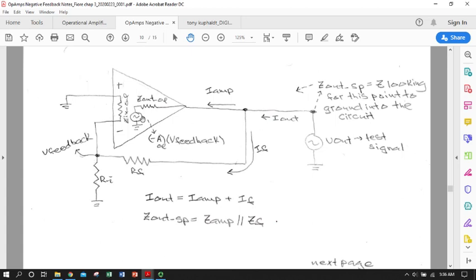and down through our representational voltage source to an internal ground. You've seen this representation of the output portion of an op-amp before. This is classic, where we have a little voltage source that is equal to the open loop gain times V feedback. And in this case, V feedback is V error, because we've grounded the non-inverting terminal.